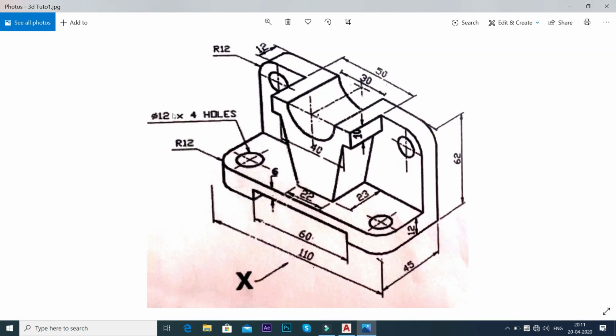Here you have got a multi-leader available. So this is another way of dimensioning. So as you can see that this is a multi-leader, and this is not aligned to a particular plane. Instead, this leader is aligned to the view plane of the object. View plane means the plane which corresponds to the screen of your computer. Okay, so that is the view plane. Here also you have got one radius option available. So these two are on view planes.